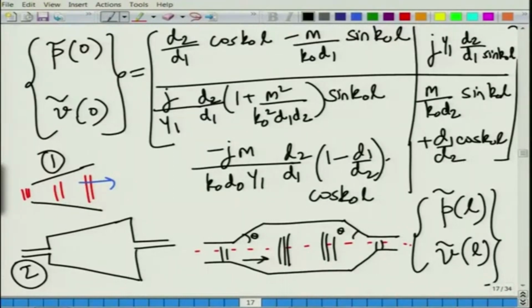So, what we could do for such more complicated test cases is make use of the transfer matrix between, say, this section and this section, this section and this one and this one, then this one and this, finally from here to here. So, it becomes as simple as cascading or sequentially multiplying the transfer matrix for a given element. These are clearly uniform sections, where I have marked with the orange thing; these are diverging or varying sections, converging or diverging in nature. So, one can figure out the transmission loss of such a composite configuration.